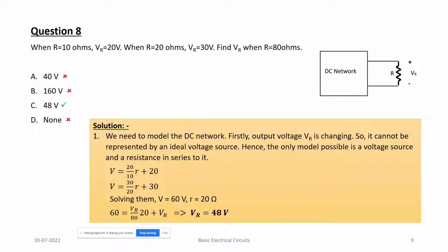Okay, now please tell, how will the resistance come across? Will it be parallel to the voltage source or series to the voltage source? Series to the voltage, sir. Why not parallel? A current source has a parallel resistance, and a voltage source has a series resistance, right? Yes, you are absolutely correct, but why not parallel? Tell it logically. If it is parallel to the voltage source, what will happen?